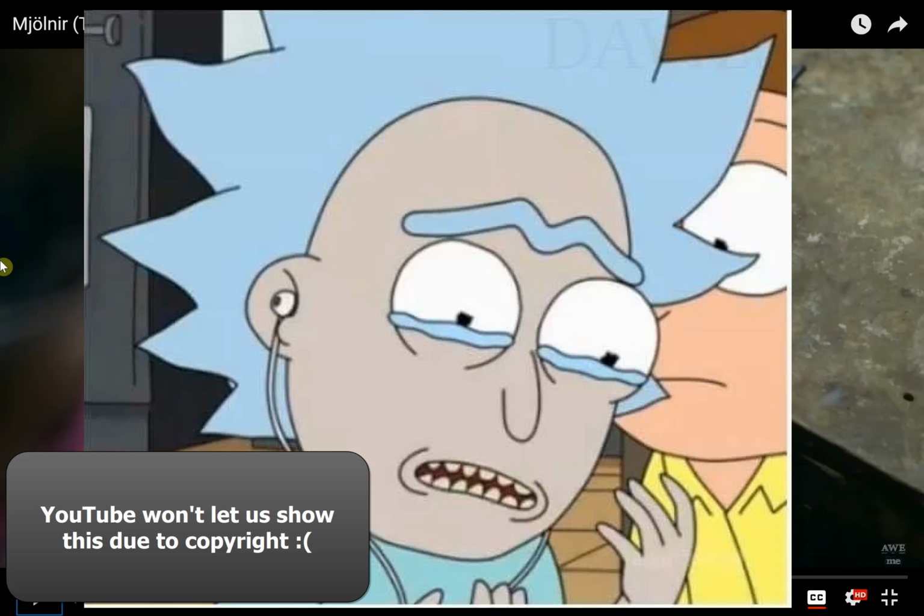That's what I think, right? You're applying the same stress to the whole plate. If you're bending it, the whole thing's got some bending moment. But if you've reduced the cross-sectional area, then the local stress there is greater, and it's going to yield first. That make sense? So I think that's what's going on there. Okay? So they've scored it.